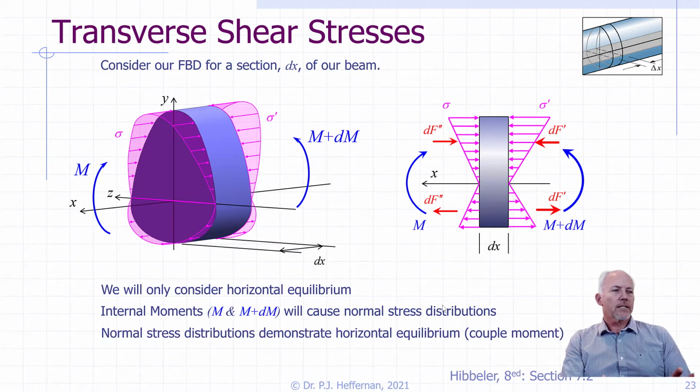So these stress distributions, of course, their integral is what creates the internal moments, the M and the M plus dM. And so we can represent those moments as force couples, dF double prime and dF prime, compression and tension on either side. And that concept of those longitudinal forces resulting from those normal stresses, creating that moment, is what's going to allow us to look at equilibrium.